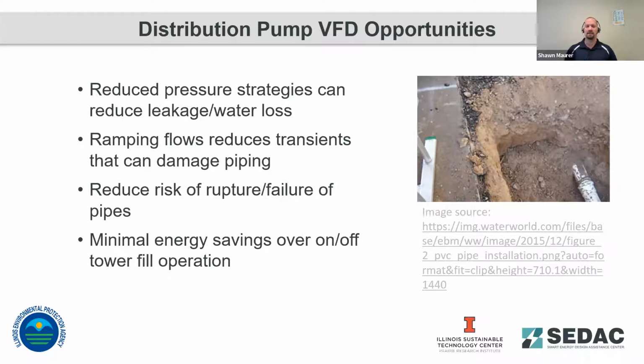Generally, what we find is if your water system is maintaining pressure through a water tower, unless you've got excess storage capacity, like a groundwater storage tank or multiple water towers, there's generally minimal energy savings that can be obtained there because you do have to maintain a certain amount of water volume in storage for emergency situations like a fire, so fire crews can hook up the hydrants and have adequate water to serve the system.